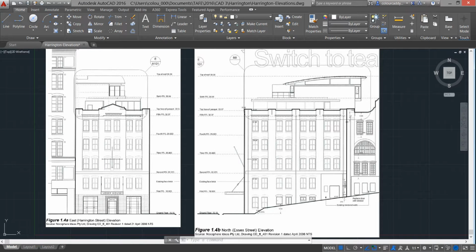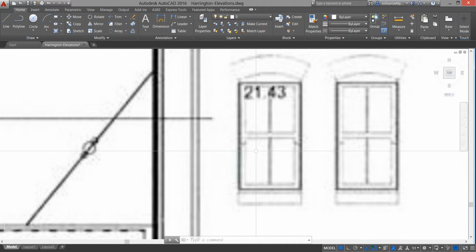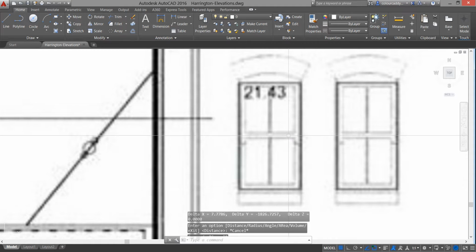Okay, so now you've got a reference that you can use to take all sorts of measurements from the levels that we're going to work with initially, so the various heights that we want from the ground, but also you can even take detailed measurements for your windows, lots of other things. So here you can see I can easily measure off this to get my window height. So they're 1825, 1830, something like that would be good enough.